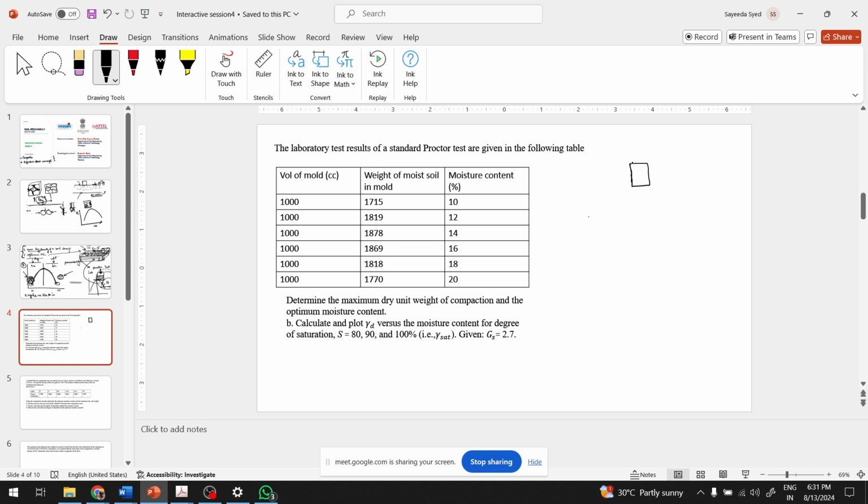You get the mold, and you get some soil in a dry state, most probably, and you add about 8% of water to this soil, such that, because this is dry, it comes to a water content of 8%.